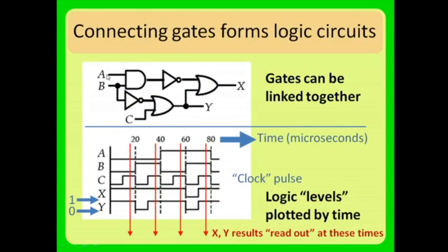Here's the way it usually works. A computer has a clock that pulses every fraction of a second. During the fraction of a second between pulses, this time state, certain signals might appear and certain outputs might appear. In the next clock pulse, the signals here may change, having been driven by other gates, and now a different set of signals appears and a different set of outputs. So the clock pulse dictates the speed of the computer, and when you see something like a chip that's rated at 1.6 gigahertz, we're talking about 1.6 billion cycles per second. That is, these changes in the signals.